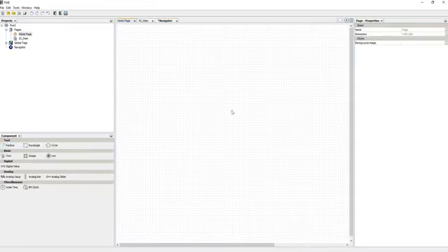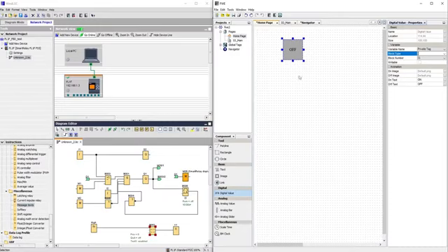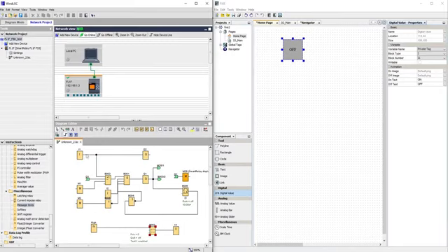We'll design a few blocks over here, as we have shown in the initial stages of the tutorial. So initially I'll drag and drop the digital values. Okay, I have done it side by side so that we can easily understand what exactly I'm trying to do over here. So I1 over here, I'll try and map to the digital value over here, which I've taken from here. So block type is I and the input is I1.